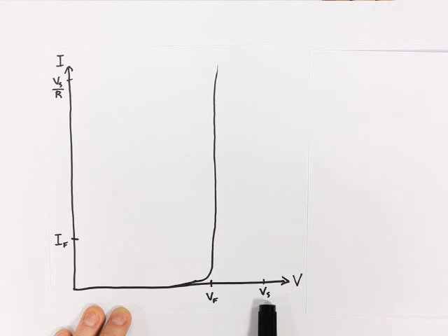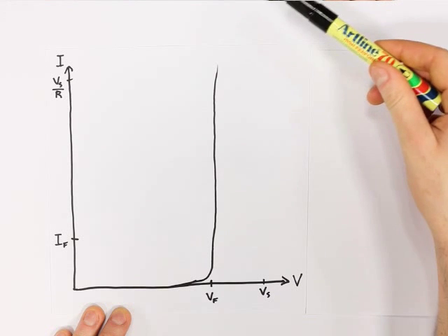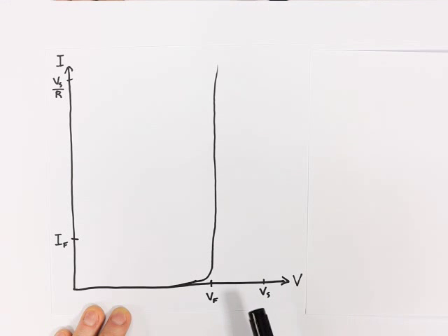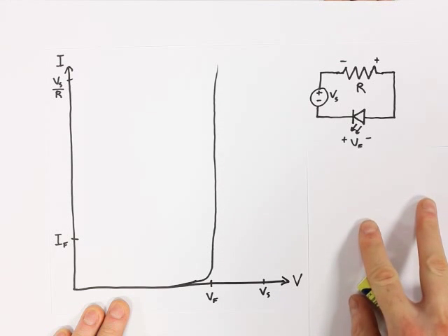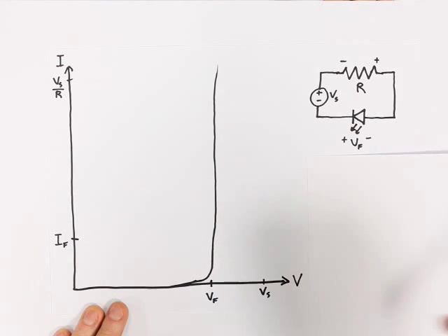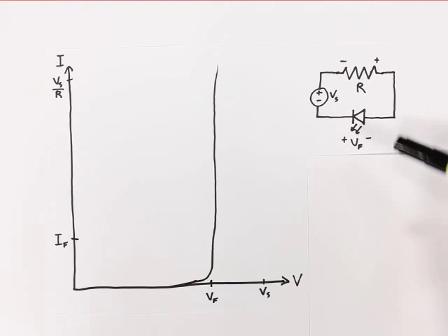If we were to just put a voltage source, Vs, directly across the device, infinite current would flow, or perhaps more realistically, current would increase until the device exploded. So we need some way of limiting that. Now, the first circuit we'll look at is the simplest and the most common, just a series resistor. So that resistor in series with our LED limits the amount of current that can flow through the circuit.